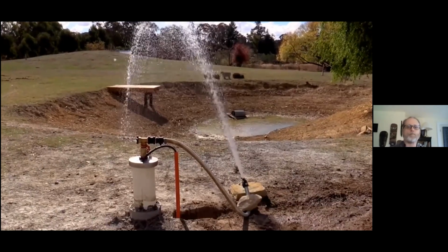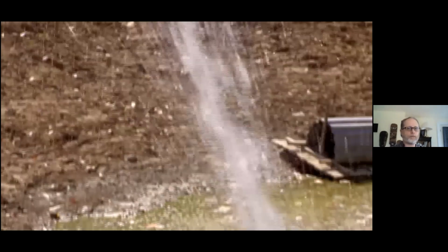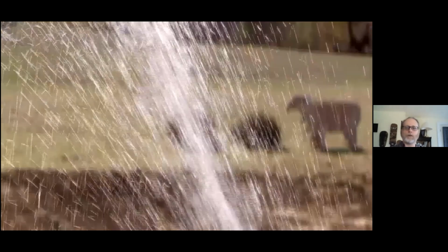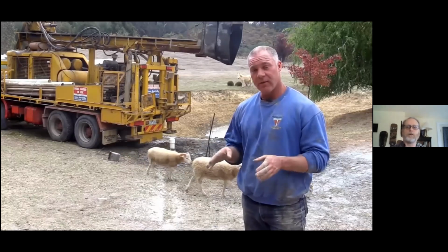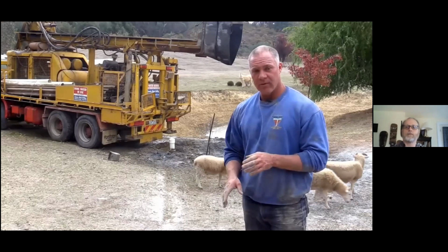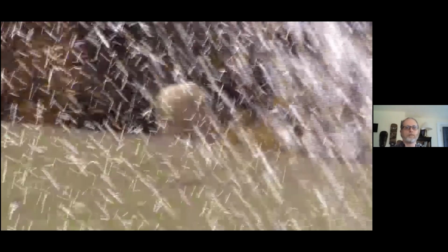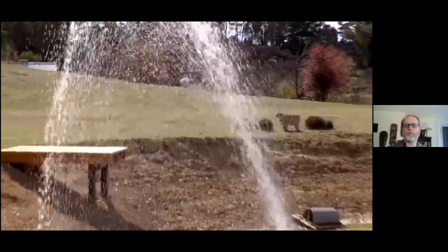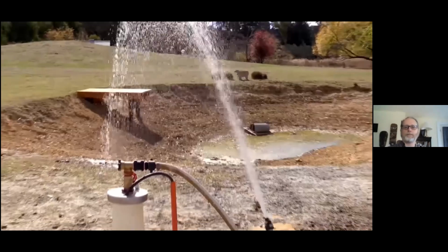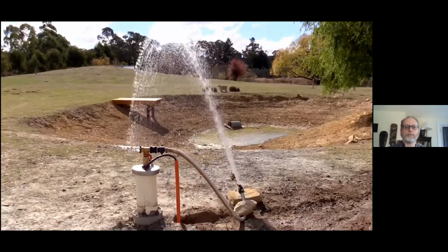So basically when we arrived, we've done the divining and we found out where there's two streams crossing, one on top of the other. That's the best place to drill, because if there's enough water on the top stream, you stop there. You don't have to go down and pick up the second stream. But if there's not enough there, you've got the option of going down to the second stream. In this case, fortunately for the customer, there was plenty of water on the top stream, and that was at about 20 metres. We got into a good flow of that, and we ran it all the way down to the bottom of that stream, which was 24 metres.